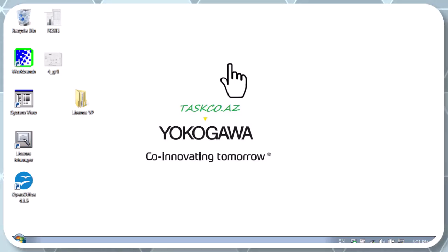Today's topic is programming liquid level control in a tank using a pump with a variable frequency drive. For this purpose, we will implement cascade control, where the flow PID controller FC is subordinate to the level PID controller LC.